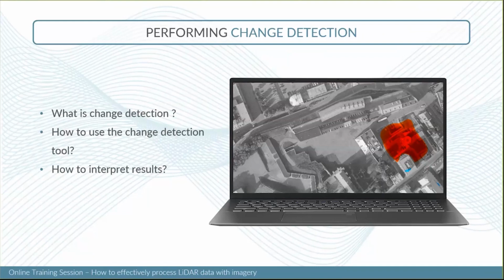You could generate a surface model from your imagery based on your LiDAR aerial triangulation, and then use this surface model and the LiDAR DTM reference, and it will give you the difference between the LiDAR and the top of your canopy, which basically gives you the height of your trees. From there you'll be able to generate other metrics such as biomass and basal area and other information from a forestry perspective.